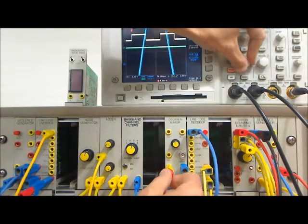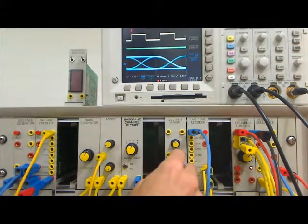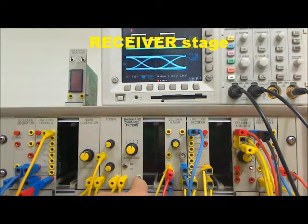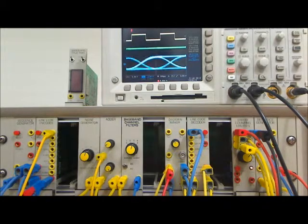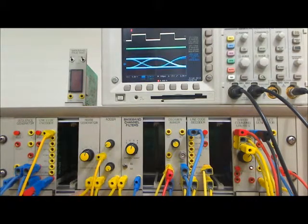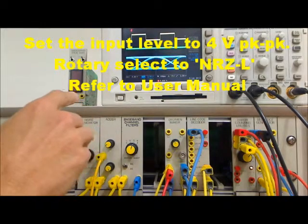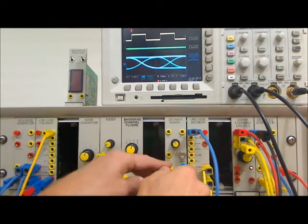Have a look at the input to the decision maker. Just channel 2, looking at the input of the decision maker. This is an amplified version of the signal from the baseband channel filter. We use this amplifier to control the level of the input signal to the decision maker so that it is set to the preferred input level of plus 2 volts peak, which is 4 volts peak to peak according to the user manual. We're on 2 volts per division, and we'll set this up to be 2 volts peak, 4 volts peak to peak, so the thresholds are correct.